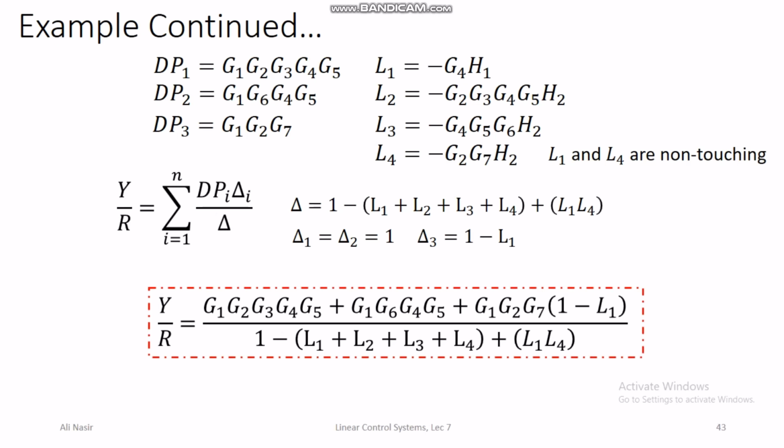Remember that if you don't have a signal flow graph, if you have a block diagram, then first you have to convert the block diagram into a signal flow graph, which is pretty straightforward, because when you convert a block diagram into a signal flow graph, all you have to do is convert all the signals into nodes and all the blocks into links. So blocks become links and signals become nodes. And wherever there are summing points or branches, you can always use a link of transfer function 1 in the signal flow graph.